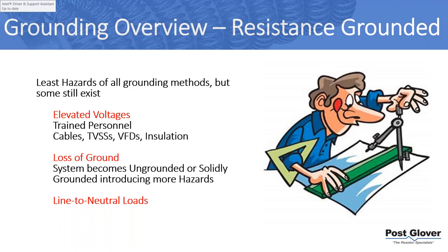At low voltage, I'm not saying it's not an issue. It's not an issue with cable, and a lot of times it's not an issue, because a lot of your equipment is already rated for that. However, it's something you need to check. It's good practice to specify high resistance ground and tell your providers, look, we're using that system, and they may give you the same exact thing, or they may give you a slightly more insulated piece of equipment. Depends on what they do.